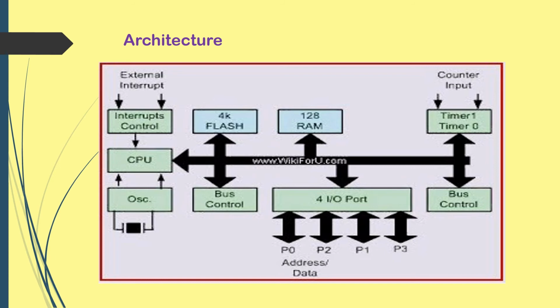If we brief about the major units in short, the ALU is the primary component. This is the arithmetic logic unit which carries out all the logical and arithmetic operations: addition, subtraction, AND, OR, XOR, and so on. The program counter is the PC, a 16-bit register with no internal address.